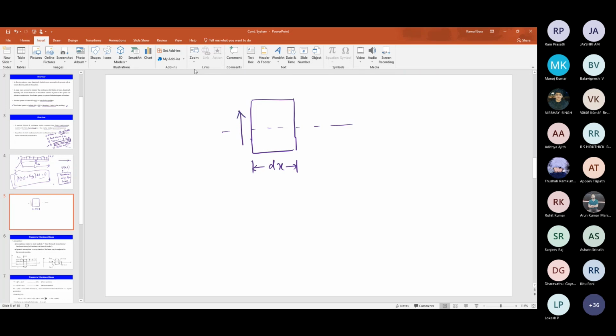So this you have already learned, right? V is the shear force. This is V plus dV, the positive sign convention. This is the moment. In statics also you do like this, right? M plus dM. And here is the distributed load, arbitrary type, f of x comma t. Dx is there. Any other force? No, right? So these are the forces acting on the element.